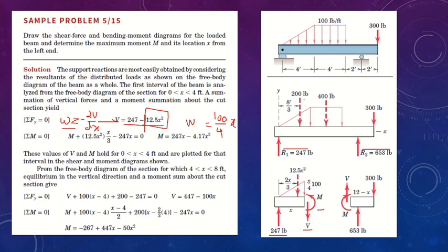Now we are going to develop an equation of moment. An equation of moment is developed the same way as shear force. We know the moment is the sum of forces acting clockwise and counterclockwise about the left end of this point. So sum of moments about R1 are to be considered from here.